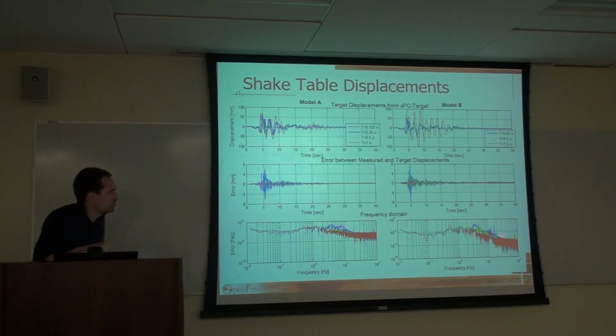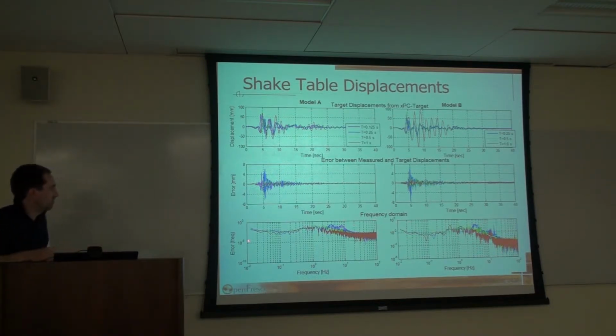One thing it's hard to see, especially probably in the back here. If we look in the frequency domain and we look at the error command, which is this command in time domain, and we plot this again as an FFT in the frequency domain, you can see exactly what Zhang Gao was showing too in his presentation. For these multi-degree of freedom systems, this one is the 3 degree of freedom substructure. This is the 1 degree of freedom substructure. So for this multi-degree of freedom system, you can see we're starting to have these higher mode errors there that really start feeding into our response, which were not present over here, right? So you didn't see those there. Now they're appearing here. So that's because of errors.